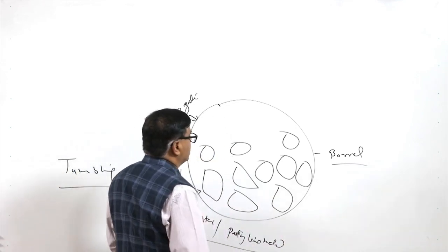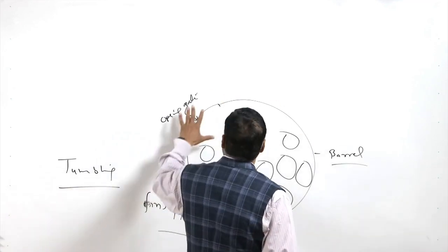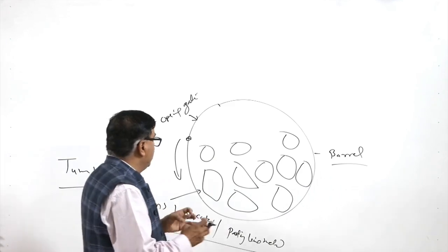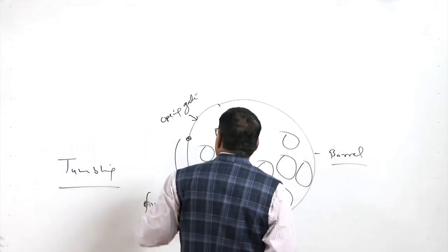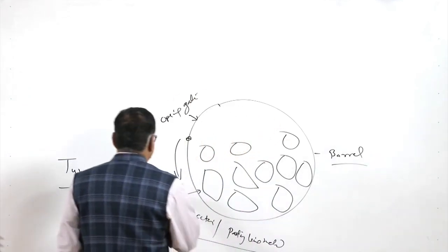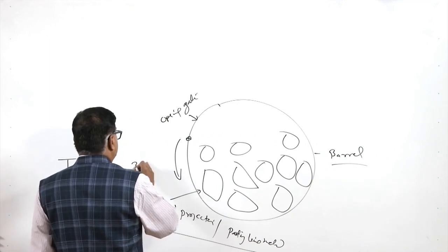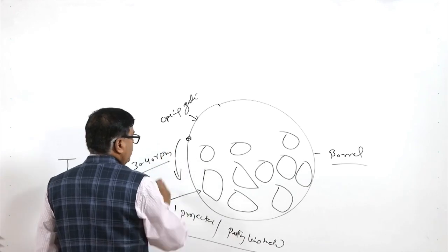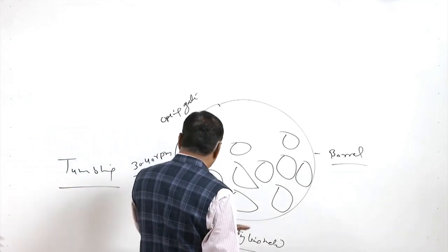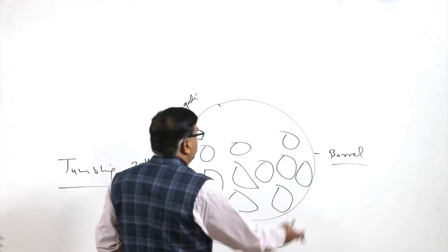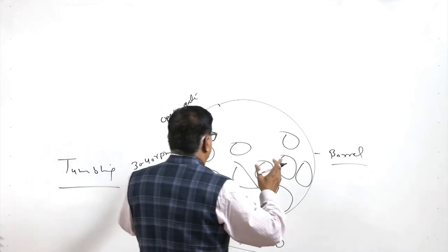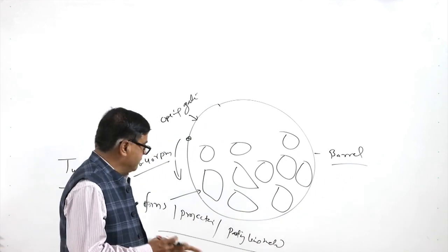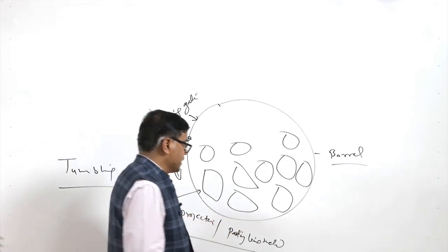Even the fused sand is easily cleaned when the casting surfaces are rubbing with each other, and the barrel is rotated at quite low speed like 30 to 40 rpm. This is the kind of speed which is used. Continuous rotation of the barrel leads to the rubbing of the surfaces of the castings with each other, thereby removing all these things.